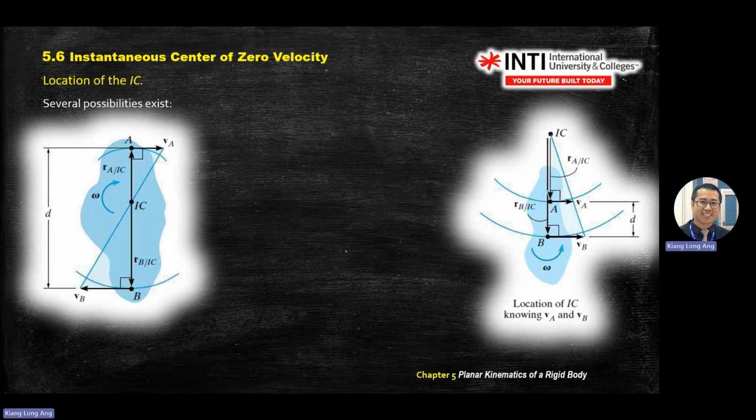This is another diagram, same approach. You pick two points. This one rotates in this direction. You draw the circular motion, then find the tangent direction velocity for A and for B. Then move your ruler corner to the A position, draw one line. Move to B, draw one line. So here the intersection will be somewhere here.